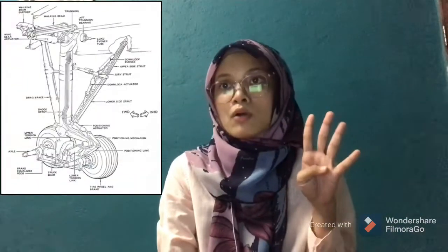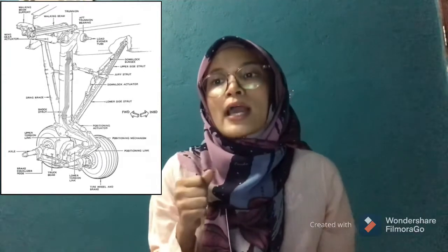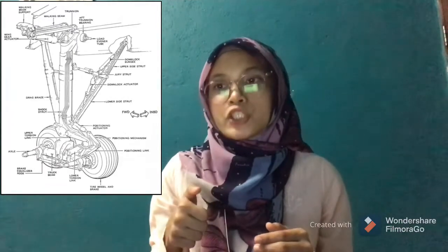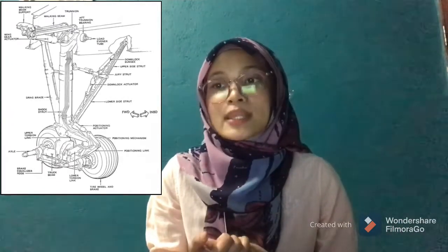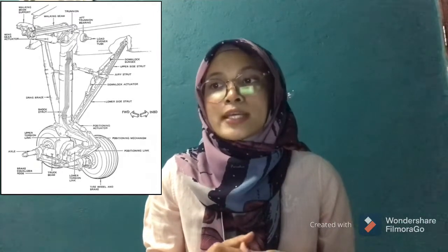Number 4 for landing gear main components is the over center link, or downlock strut, or jury strut. The function of the over center link is to hold the drag link and the side brace in the down and lock position by applying pressure to the center pivot joint in the drag or side brace link. It operates hydraulically by a bungee cylinder or mechanically by a bungee spring.